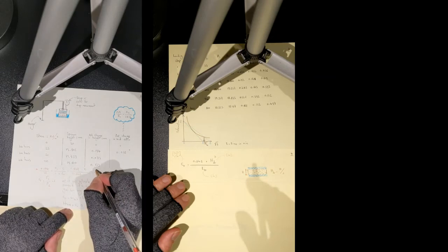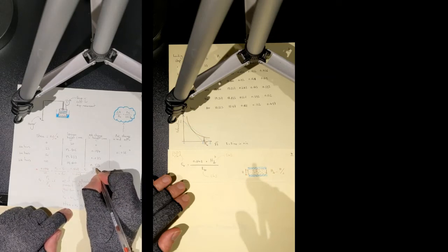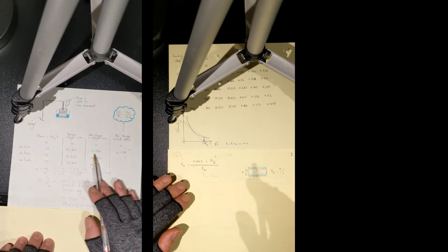Here what I have put is 0.648 minus e, which is delta e, and that is equal to 0.16, and I've brought it here. You can also determine the secondary void ratio at the end of the first phase of loading.